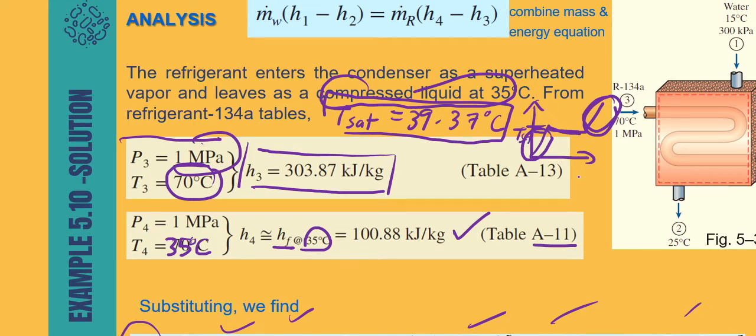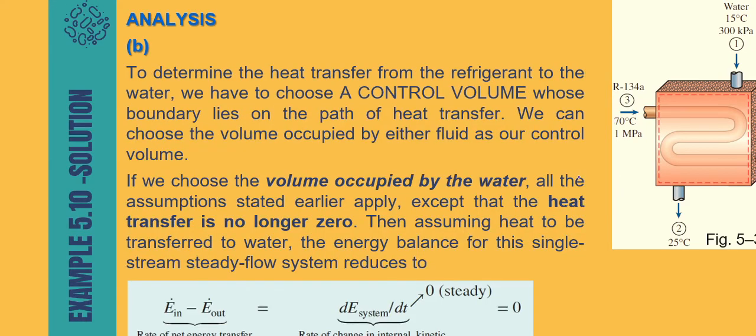That's why it is important to know the state of your fluid, whether it is saturated liquid, saturated vapor, mixture, compressed liquid, or superheated, because you're going to find the value of enthalpy. With this information, we know which table we need to refer to. So next, you need to determine the heat transfer.